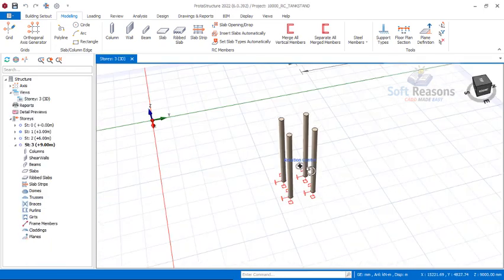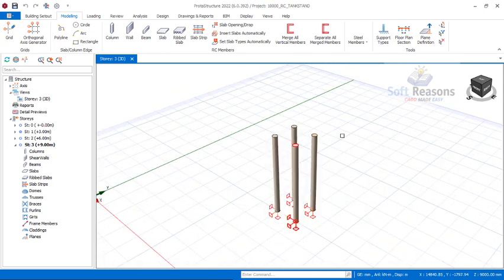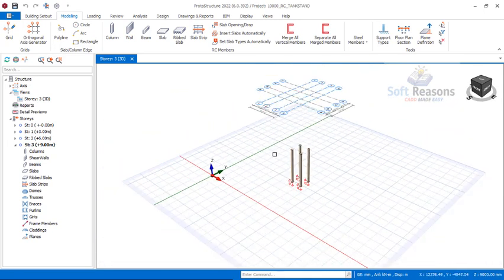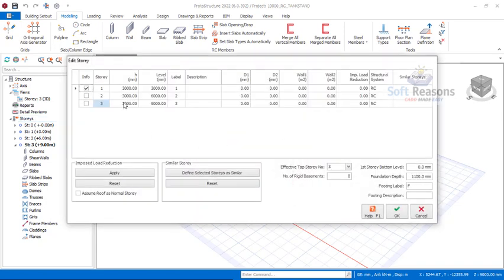Having this successfully, we can also generate this to the top, but before then let us set the story height. You click right there and right click on edit stories. In the edit story dialog, the story 3 height is going to be 1 meter. The 1 meter is the length of the railing, take note. The depth of the foundations, we will leave at 1,100 millimeters. The structural system is very important, so make sure you always check here. It's all RC. In case it is steel, you have to select steel for proper analysis and design. Click on the OK option right there.